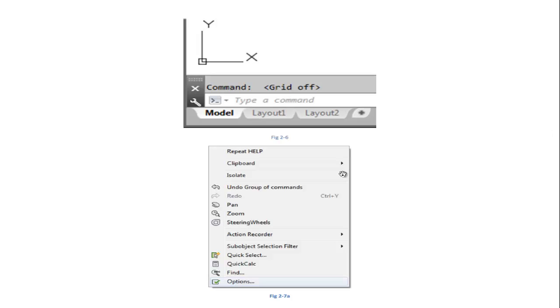Again, down at the bottom we have model, layout, and the user can switch to the model space or a layout by selecting the model or layout tabs respectively from the lower corner. If I select model, this is what I'm going to be drawing full scale on the screen. Everything I draw here, if it's a foot long, I'm going to say it's a foot long. When we get into our layout, that's basically what we refer to as our paper space. This is where we place our model into the paper so we can send it out.